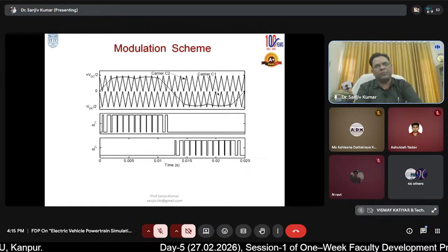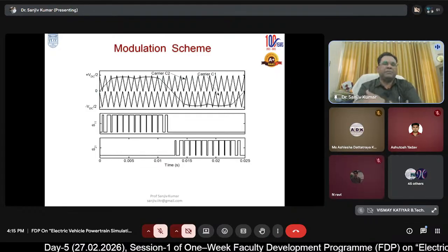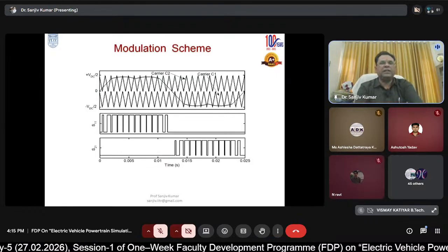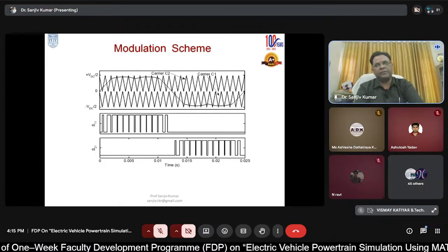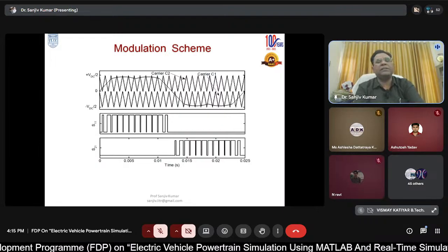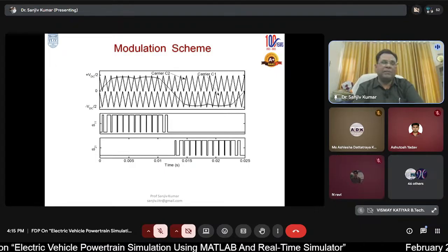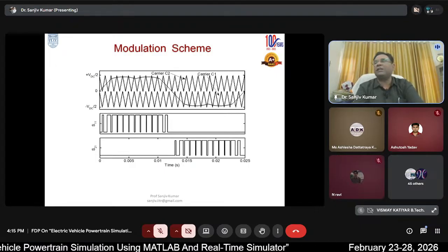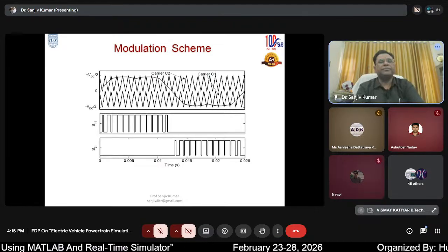Because the voltage profile gets improved, meaning you can use the maximum DC link voltage, right? It's 0.866 of VDC, but as the number of levels increases, it is very difficult to identify the sector and triangle number and all those things. Those who are working in the field of power electronics know what I mean.